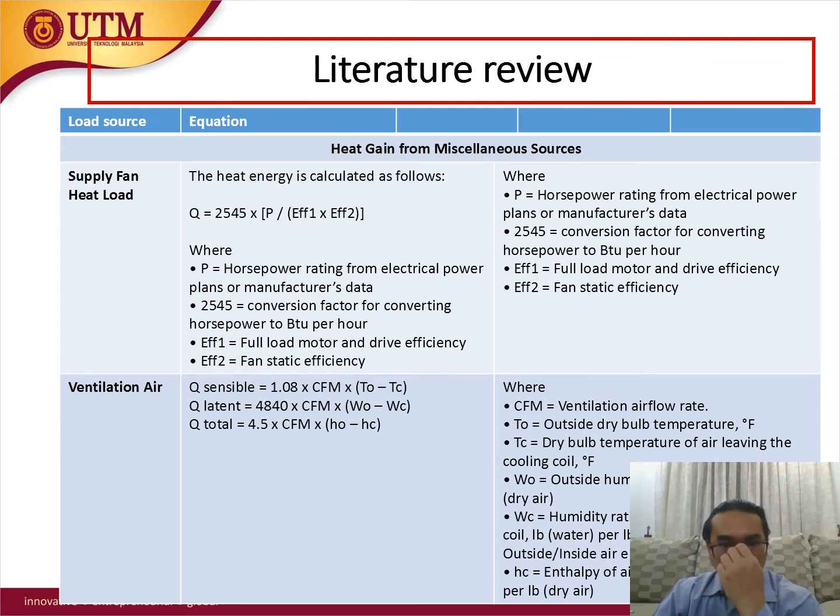Ventilation air. Ventilation air is the amount of outdoor air required to make up for air leaving the space due to equipment exhaust, exfiltration, and/or as required to maintain indoor air quality for the occupants. The heat is usually added to the air stream before the cooling coil and has no direct impact on the space condition.